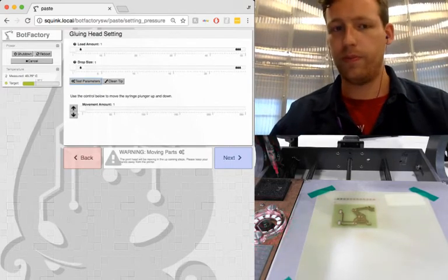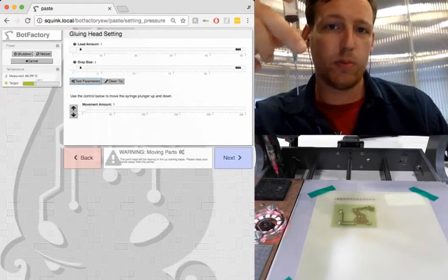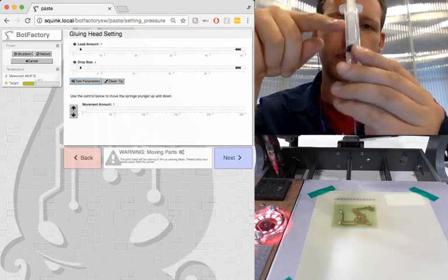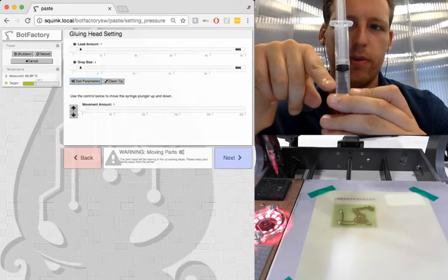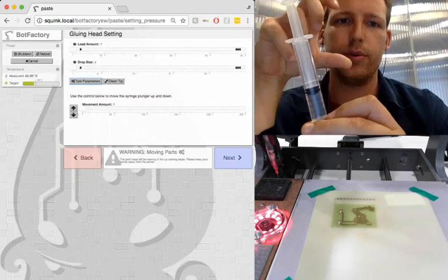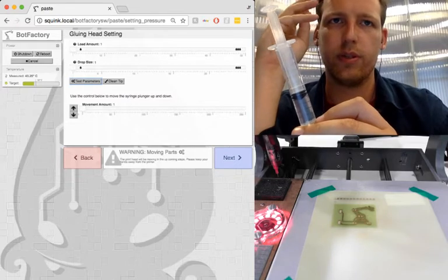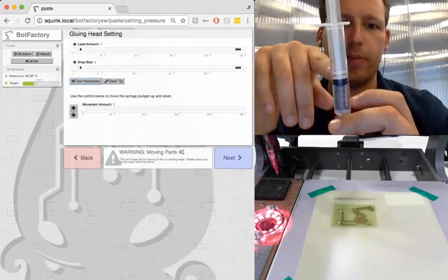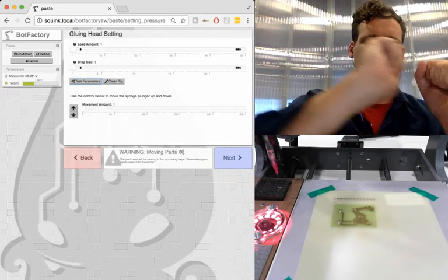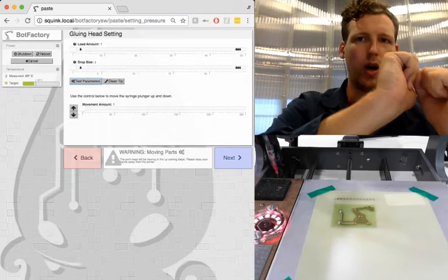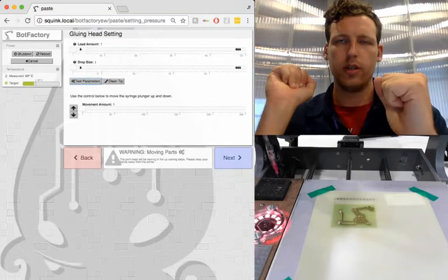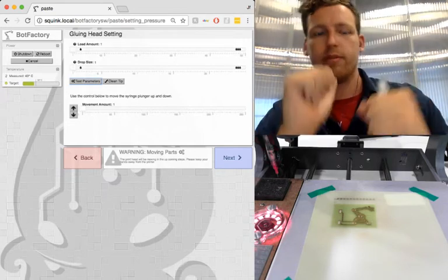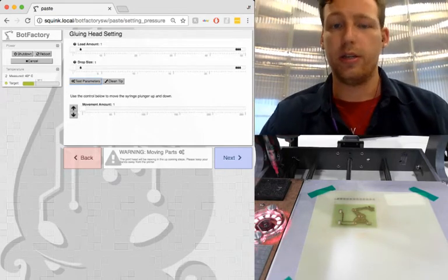The way our dispensing system works is it goes down a set amount and then retracts a little bit to ensure that the fluid does not flow out too much. But we don't retract completely backwards. We're not pressing it down by 1 and then pulling back by 1. Typically we're going to press down by 1 and then retract by, let's say, 0.8. And that is what essentially these numbers mean.